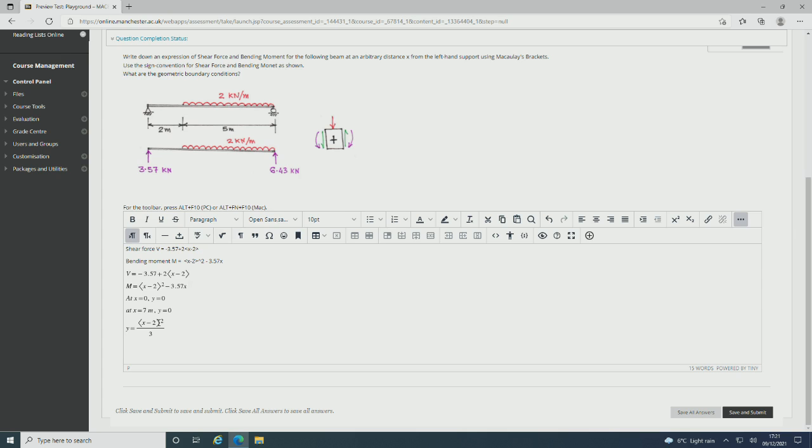Now if you calculate, both have the same area, the same amount of material, this one will have a higher I value because more material is away from the central axis. Okay. So use that idea there.